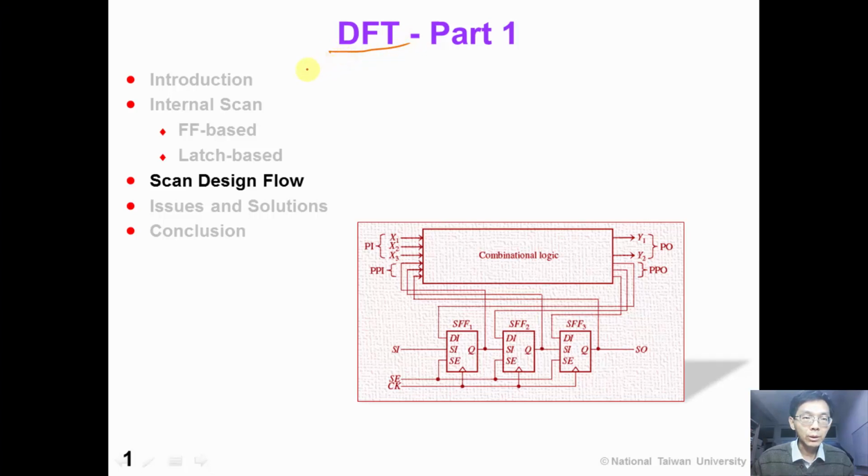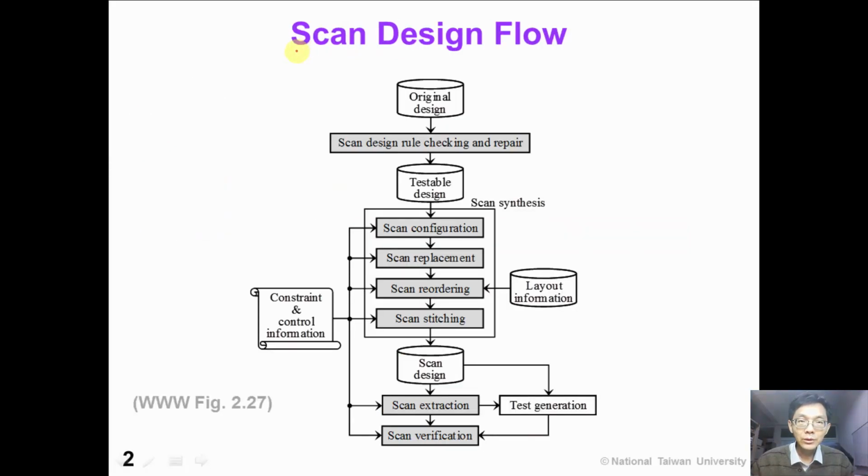In the previous video, we have introduced the concept of flip-flop based scan and latch based scan. Now, in this video, we will introduce the whole scan design flow. This slide shows the scan design flow taken from the W textbook. The scan design flow converts the original design into a scan design.